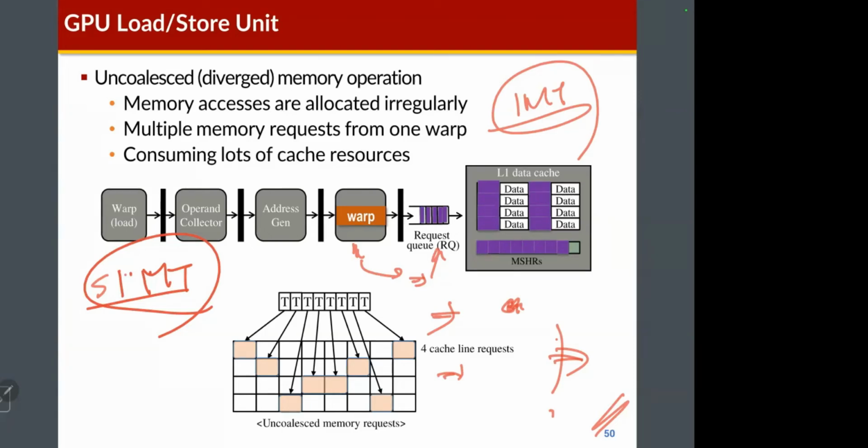But with the SIMT, you can think that these threads can be executed individually. It's kind of an illusion actually. GPU supports the SIMT programming model, but the inside of the GPU is designed like a SIMD. So it's a kind of wrapper of the SIMT.